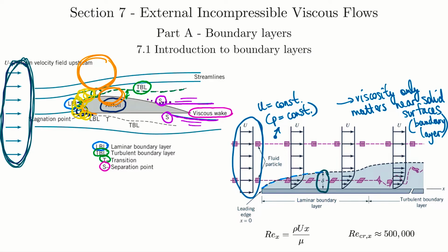And now it becomes evident that above this boundary layer, you don't have viscous effects, because there's no change in velocity. But within that boundary layer, there's a velocity gradient where the viscous effects are going to be very important. Now, some terminology. Generally we say leading edge to denote the front. We're looking at a flat plate here. We'll talk about different shaped surfaces, but it's best to start with the most simple case.